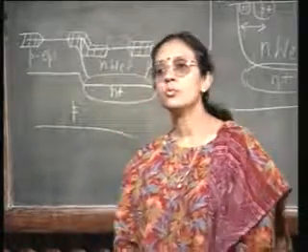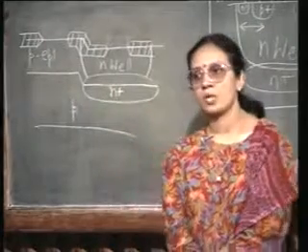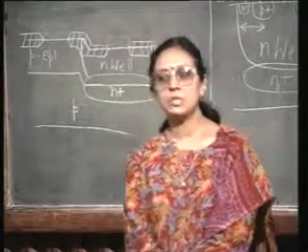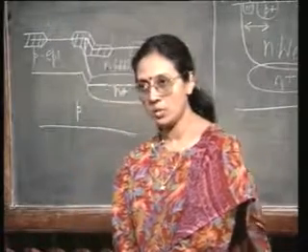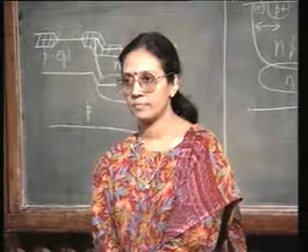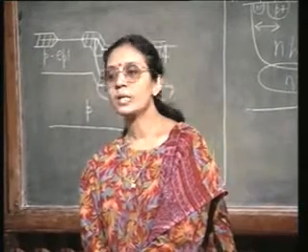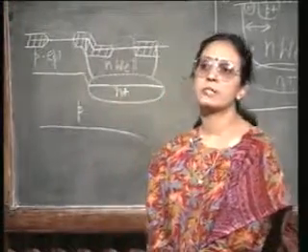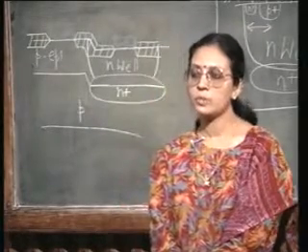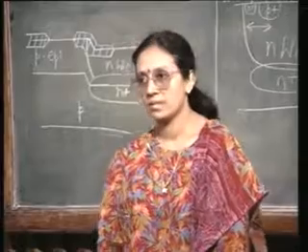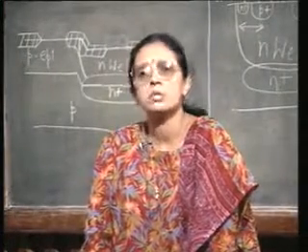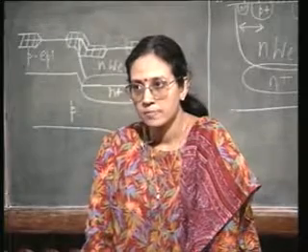But if we can think of circuits where, in a circuit essentially, what do we have? We do not need high speed throughout the circuit, right. We only need high speeds at certain bottlenecks. So, if we can conceive of a circuit where in these bottleneck regions we put in high speed devices, for example, high speed bipolar junction transistors, you know, ECL logic is still the fastest logic.